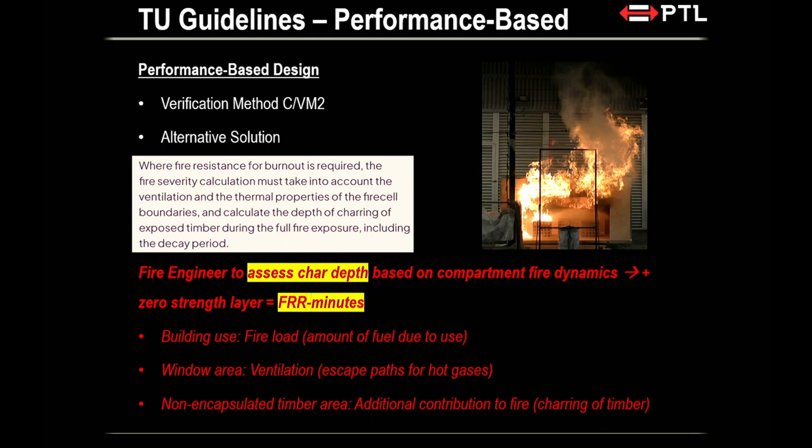The char depth calculation depends on, and this is the stuff that you know from the first few slides, the fire load, the ventilation, the amount of exposed timber. So all these factors govern the char depth. And eventually this char depth, you will use it, you will add zero strength layer, and from that determine the fire resistant rating. So a 60-minute fire resistant rating, standard charring rate, what's the char depth, roughly?